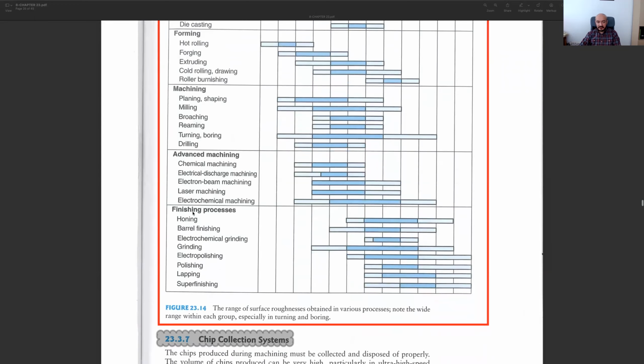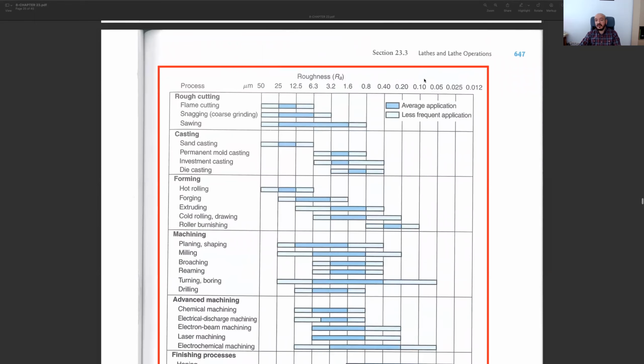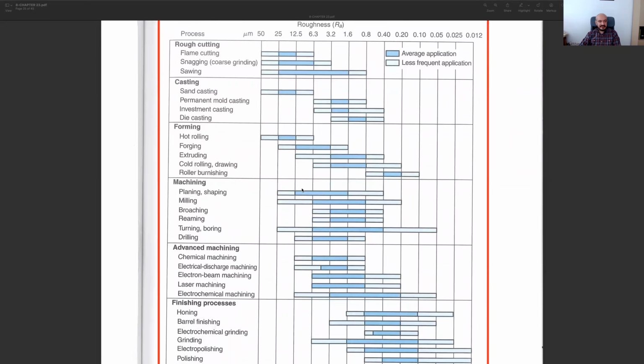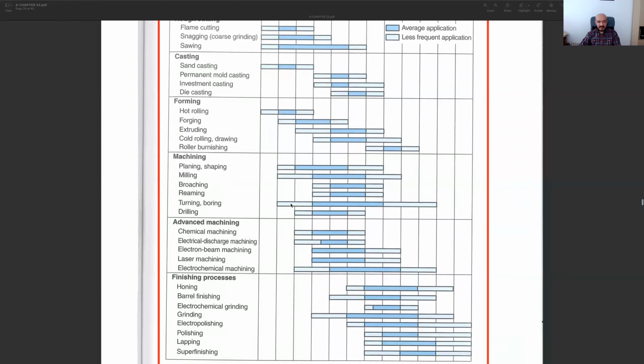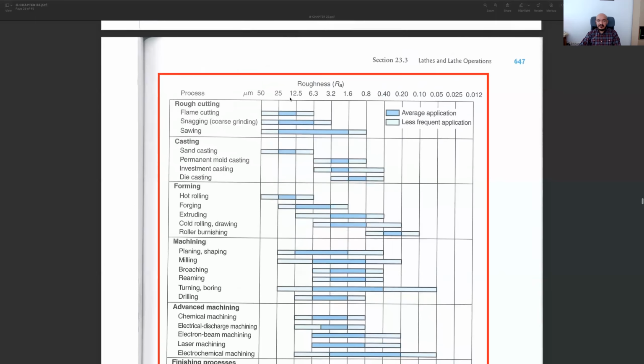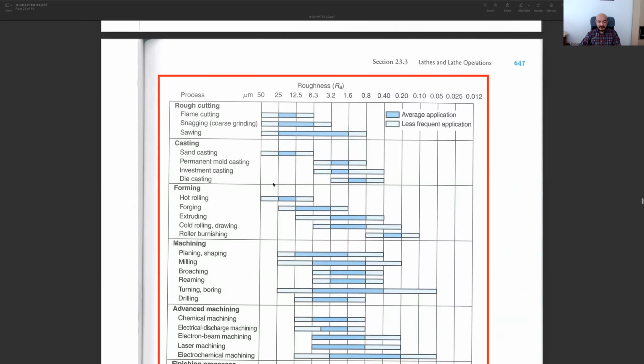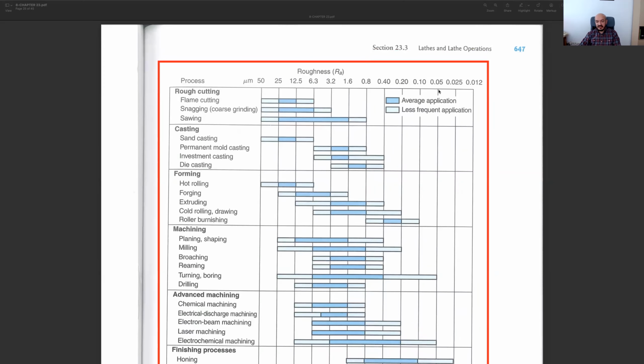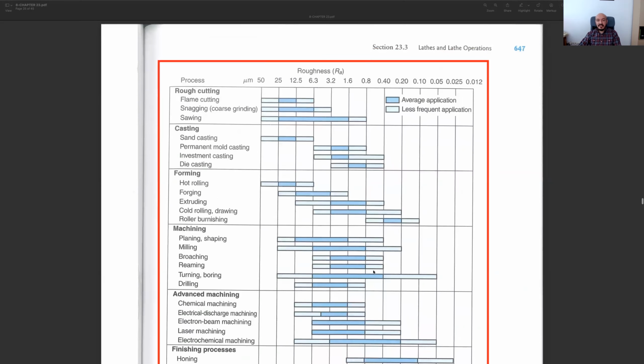But obviously, if it's a finishing operation, which we haven't discussed, the surface roughness value of your resulting part should be lower, maybe less than a micrometer. But if you do some turning operation, depending on the type of turning, you may have surface roughness of 25 micrometers or less than 50 micrometers. It depends on the type of cutting tools you are using and the capabilities of